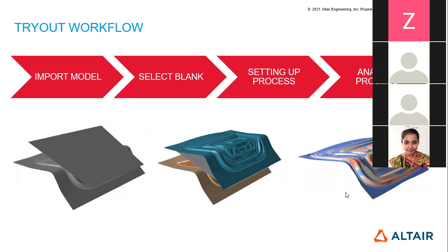Tailor welded blank is a very popular trend in the manufacturing industry, driven by customer demand. Suppose you want to form a circular sheet. Half of that circular sheet would be steel, and the other half would be brass, and these two semicircles are welded from the center. These types of blanks are known as tailor welded blanks.